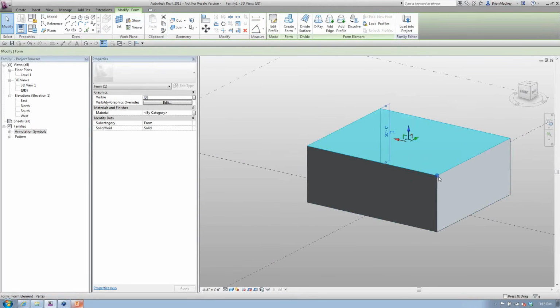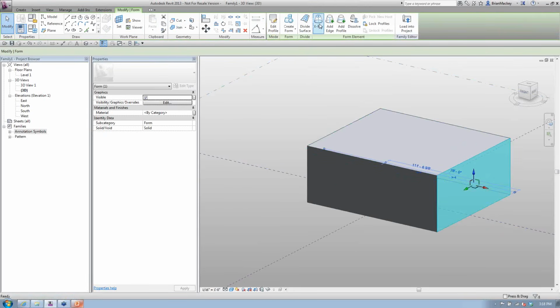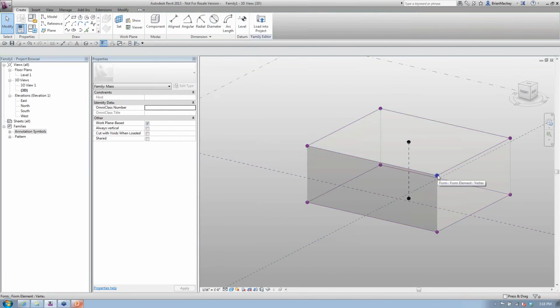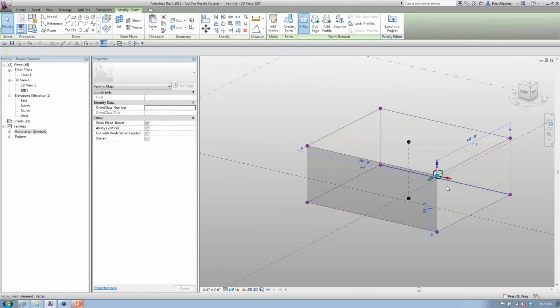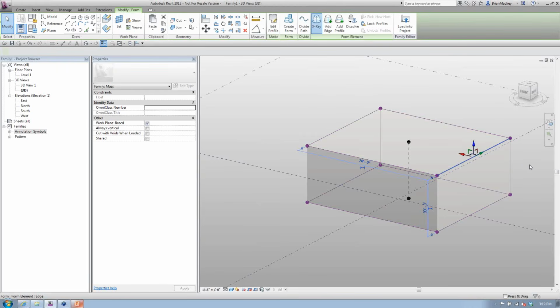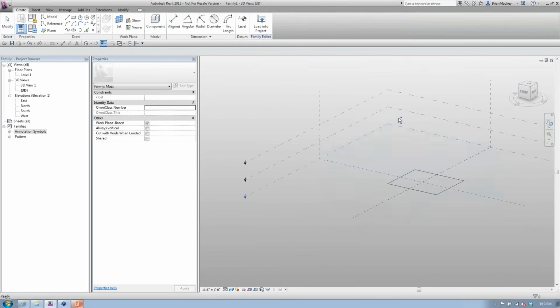And it becomes a little bit difficult to see what you're doing. Same thing for the corners. I need to grab the tab key to do that. It's much easier if you just grab any part of that mass and go into the X-ray mode, because now it's going to make those visible for you. So much easier to start grabbing the one surface of the mass and going into an X-ray mode so you can really see what's going on to get that set up. So now I can see the points without tabbing, get the edge without necessarily having the tab. Just makes life much, much easier when you're starting to do that. Thanks, Brian. So let me just Control-Z out of that again.